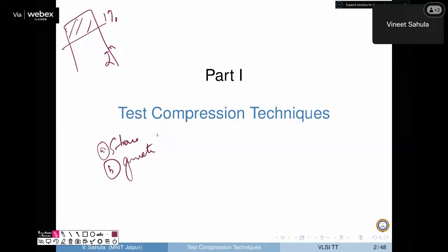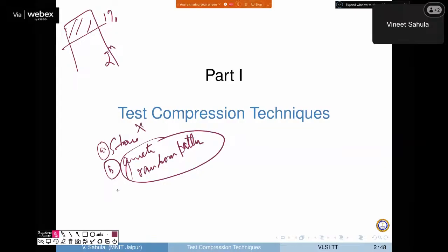If it is random pattern, we can generate the random patterns. Now this is extremely efficient because I do not need to store that and I can generate on the fly. So this circuit for generation of random numbers or random patterns should be on chip, and this is a little cheaper. And the second requirement for me was output pattern compression.